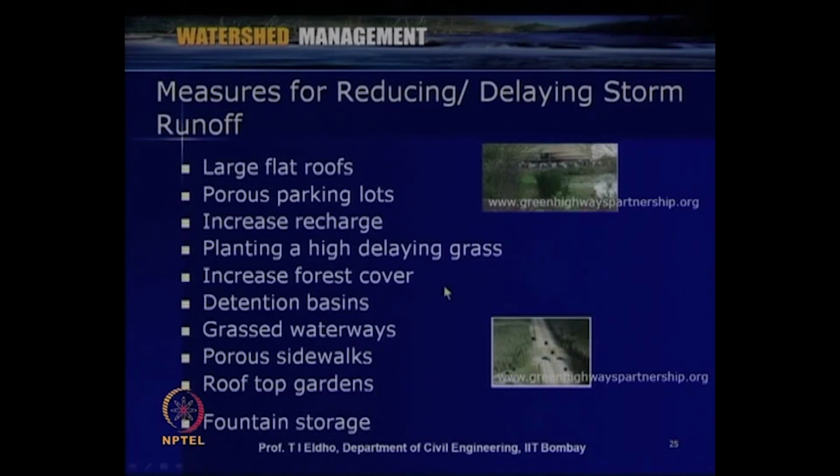In all this, what we are trying to do is delay the movement of the storm water, and infiltrate some portion of the storm runoff, and delay the movement of the runoff, so that the time to peak will be increased and the peak will also be reduced, as far as the urban storm runoff is concerned.